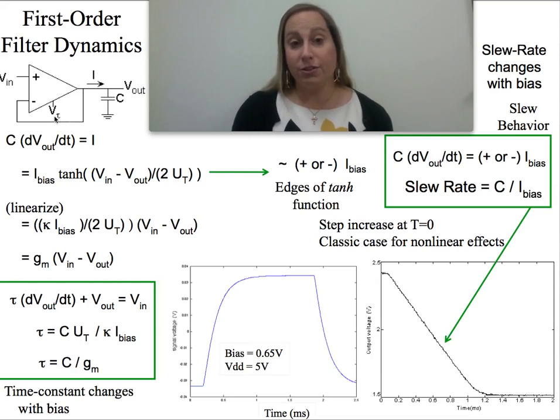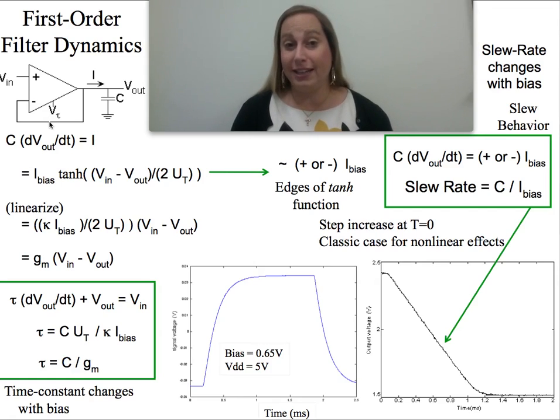What's useful about this circuit is that without this capacitor, we would know how to solve this because of the high gain: the output voltage is roughly equal to the input voltage. So we expect at DC we're going to get something roughly equal, right? And we'll see this as we go through the equations even further. But you kind of expect that.